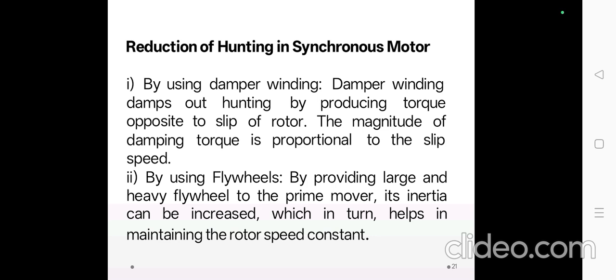If the synchronous machine is running as a generator, the phase sequence should be same as that of bus bar. The machine speed and field current are adjusted in such a way as to have the machine voltage same as that of bus bar voltage. The machine frequency should be nearly equal to bus bar frequency so that the machine speed is nearer to synchronous speed. When the above conditions are satisfied, the instant of switching for synchronization should be determined.